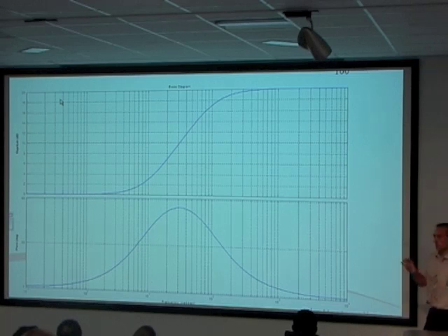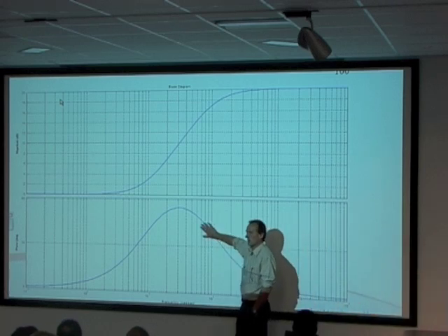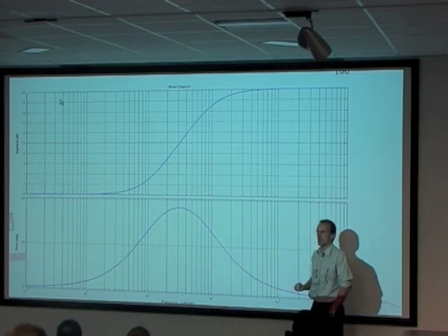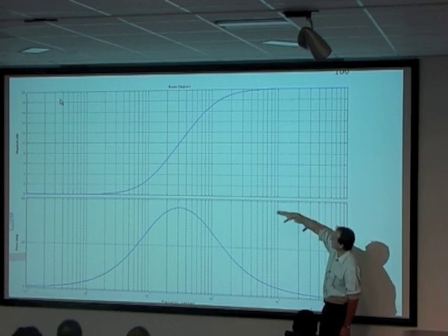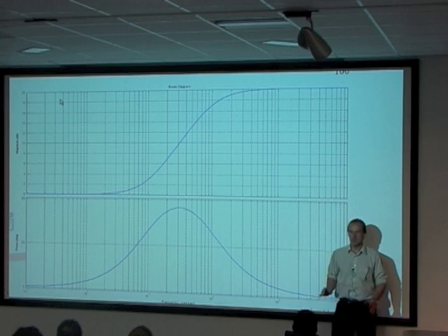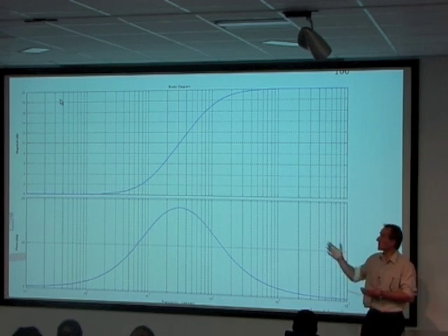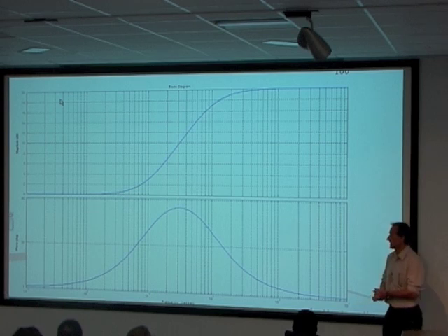So what this gives us is the ability, and in a sense the phase is the important one, to pop in a quick lump of phase advance where we need it. There is an effect on the overall gain, but we can do some interesting things just by introducing that phase advance. Does that make sense? You can see how this is built up from a lead followed by a lag, and that's a lead compensator.